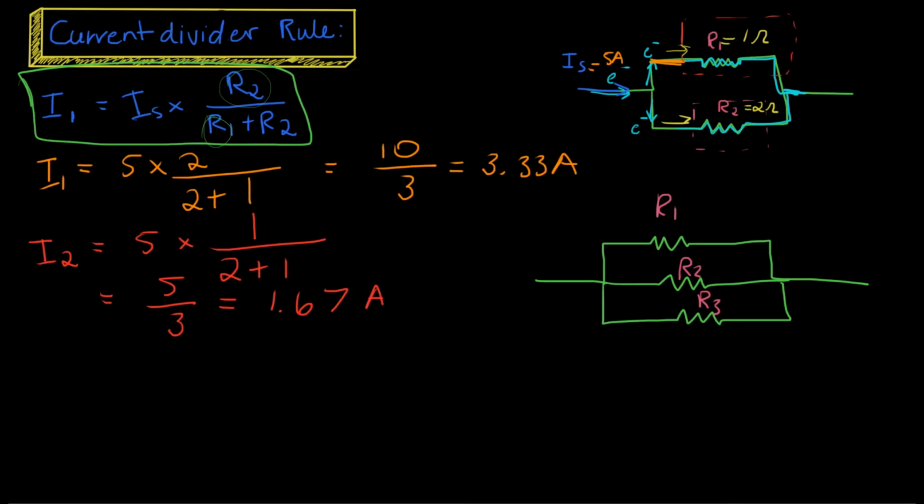What we would do is if I wanted to know what the current through R3 was, I could just use my parallel addition of 2 resistors to collapse this down to a circuit that looks like our original, like so, where this here is R3 still, and this is going to be the parallel combination of R1 and R2.